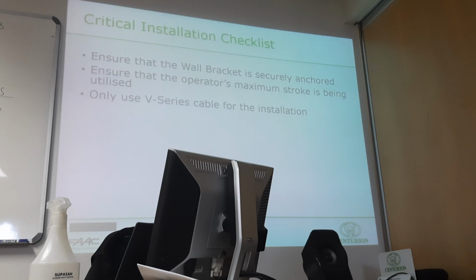So turning it back reduces the stroke out. Yes. Okay. So if I turn it back now 1, you'll see this gate will now be more open. Oh, okay. So I can actually show you guys, but you're not going to see it there. So I would say maximum minus 1, or maybe 2 turns, if you can. Yes, that's it.